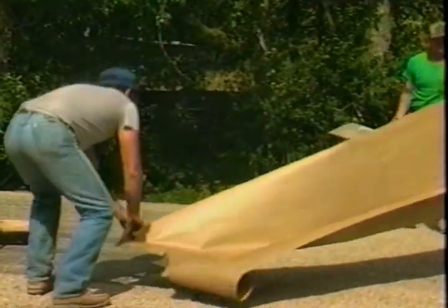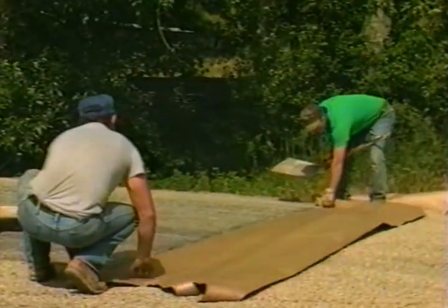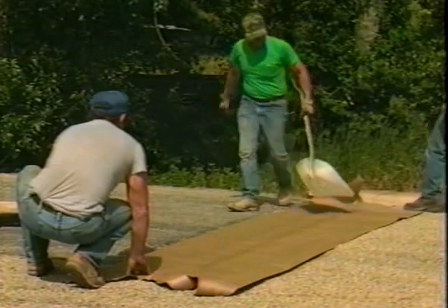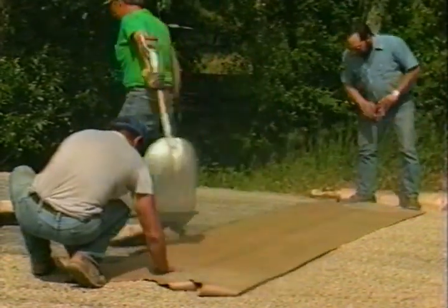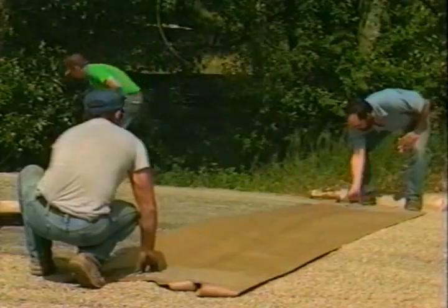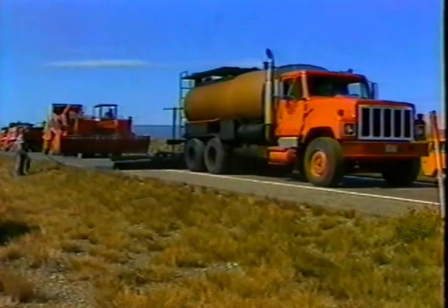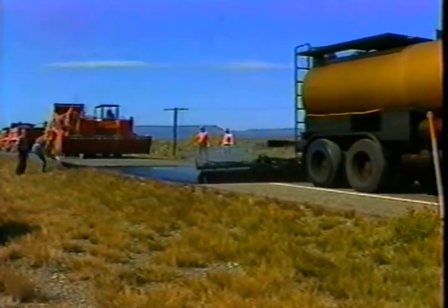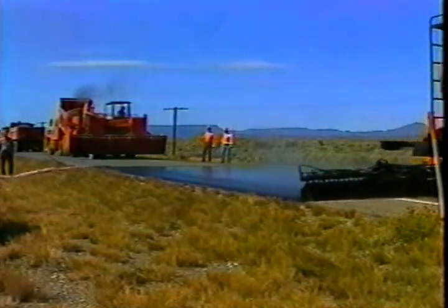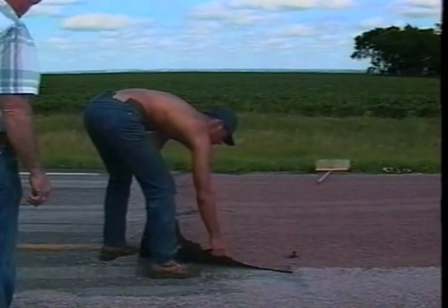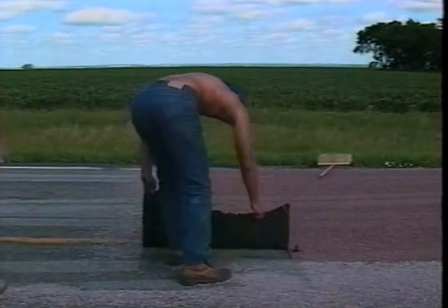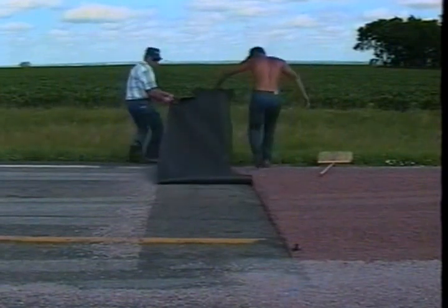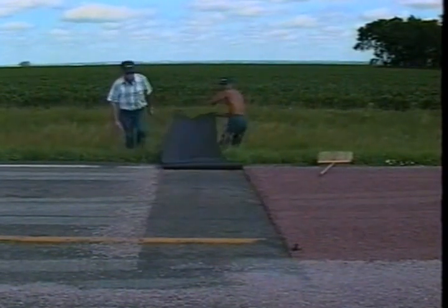As for transverse joints, every application that takes off from a previous one has to begin on building paper. The reason is simple but important. You have to avoid spraying oil on the chips already in place. If you don't start the application on building paper, you'll be placing one application over another and building a bump in the surface. As stated earlier, use building paper at the end of each application too. That's the best way to keep the edges neat and even. Be sure to dispose of this paper properly, according to the regulations in force.